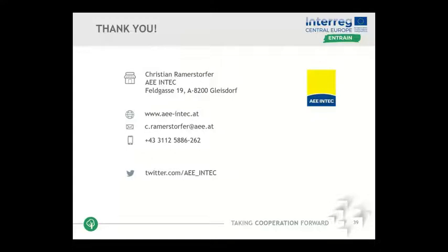What you have to consider is a backup solution, because we want to guarantee high supply security for our heat customers. And sometimes they say an oil or gas boiler is very high security to provide heat at any time in case we have any issue with one of the biomass boilers. As we know, biomass boilers are larger, have a lot of conveyors and fuel transport equipment as well. So there could be an issue, but if you plan it properly and operate it properly, it should not.